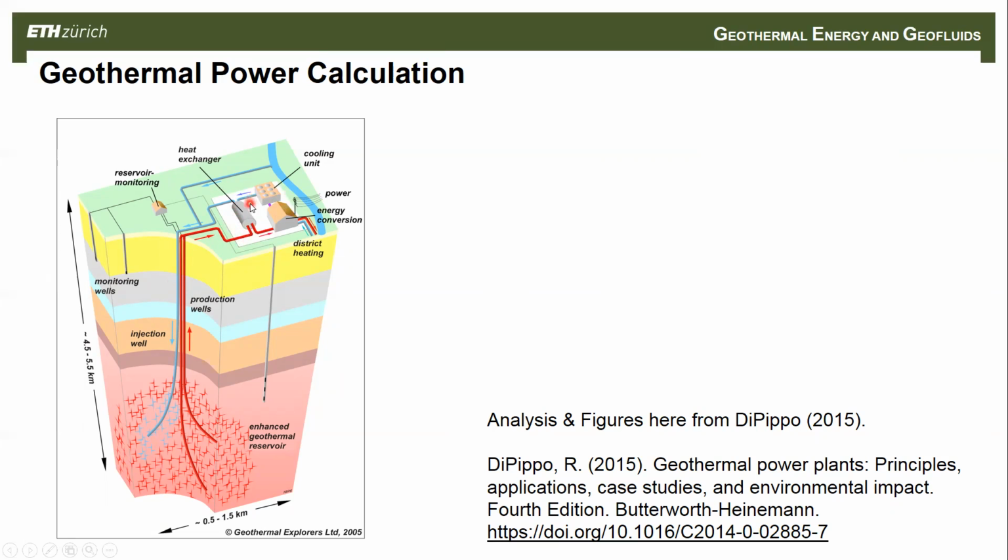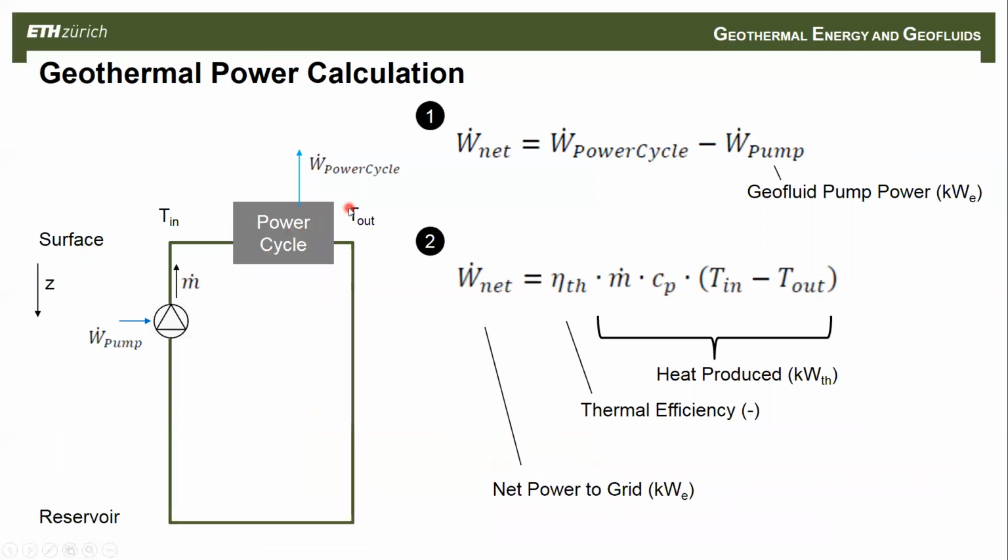So in here they have a heat exchanger. On this side you have the geofluid. Hot geofluid gives off its heat to a second fluid here. We call it the secondary loop, which has a turbine and cooling towers and everything within it. So this up here is what makes the electricity. I replaced that at the surface with just a box. This here I have as a power cycle now. This is what makes electricity that you sell to the grid.